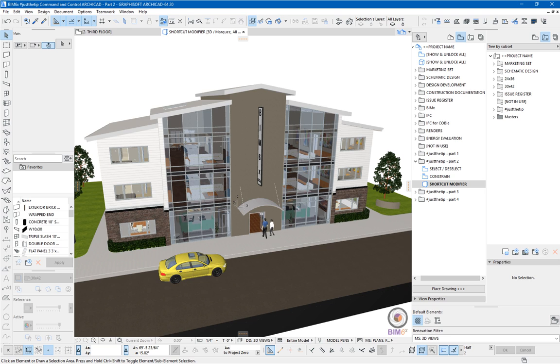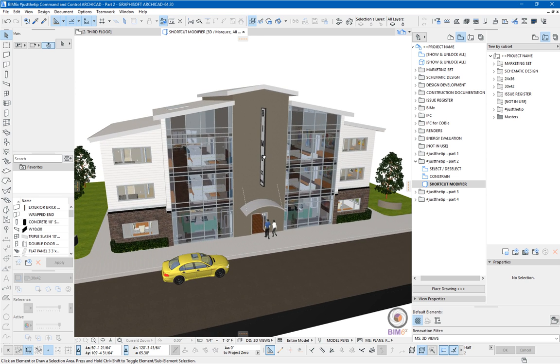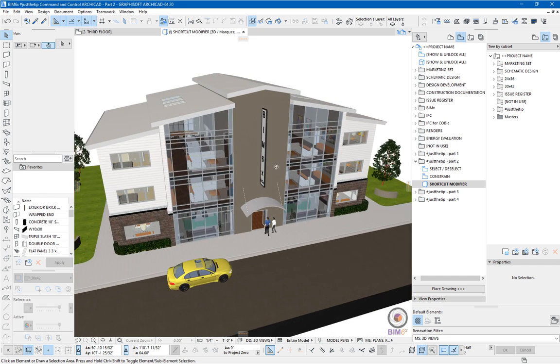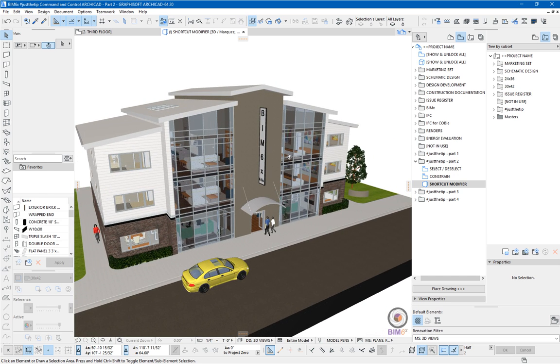Another one of my pet hates is having to find and use the orbit command either here or with the keyboard shortcut O. But instead of doing any of that, if I come up here, anywhere in the middle of the screen, hold down the wheel, I can pan. Instead of doing that, if I use the modifier, which is Shift, and then hold down the wheel.